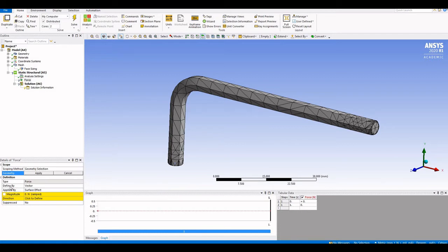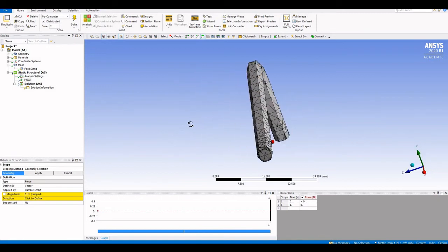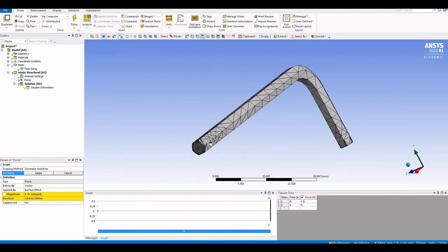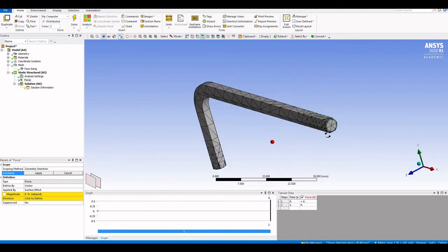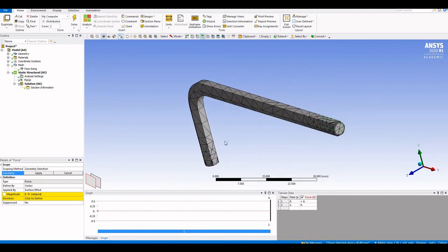So in the table created for force, first it needs the geometry that the force needs to be applied. Although we hold most of these surfaces, the fact is that our effective load is applied to the opposite side, so to these two faces. By pushing the Allen key, we apply the effective load on the opposite side to rotate the Allen key clockwise. So I select those two surfaces.